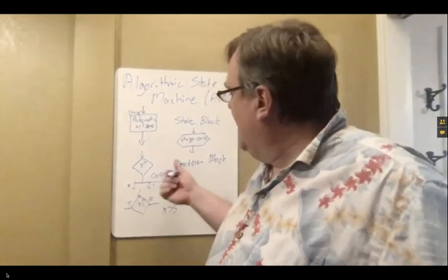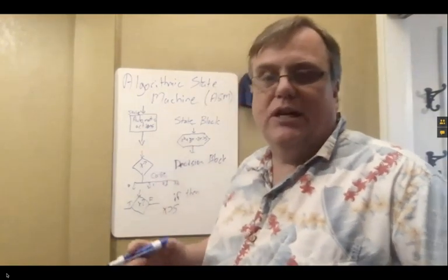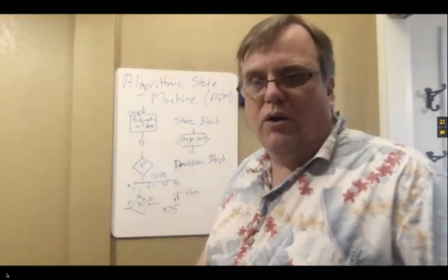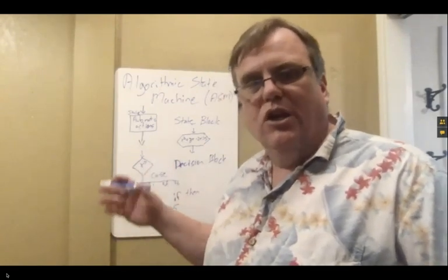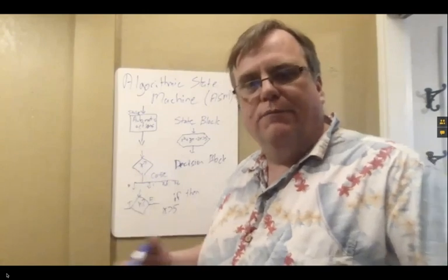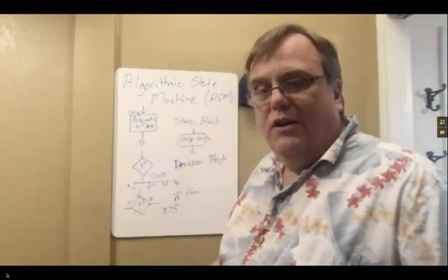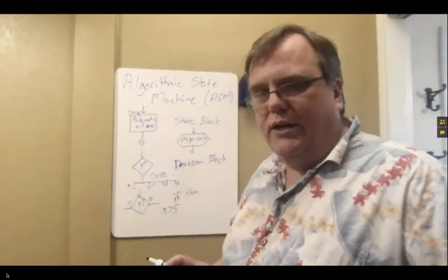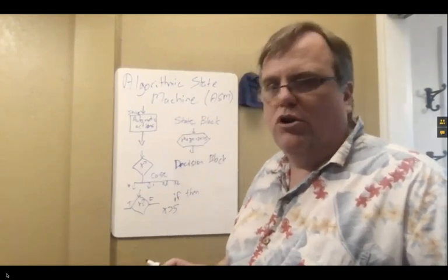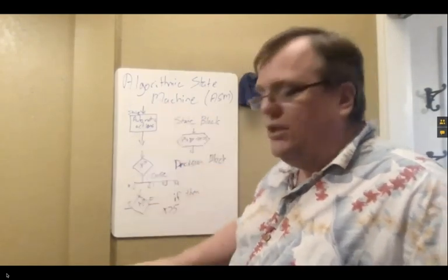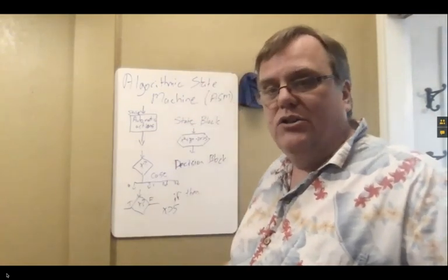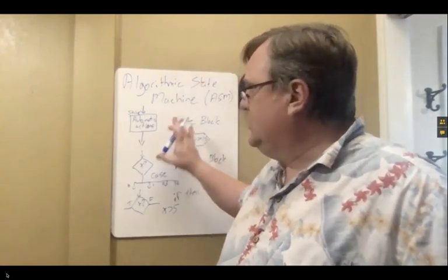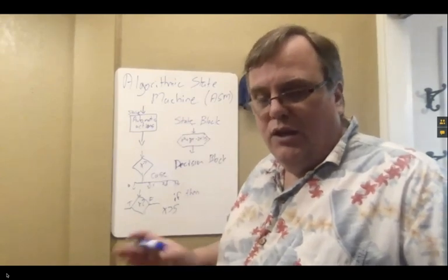The stuff today will also be very testable, which is why I wanted to rush things up so I got through this and you have time to test it, because ASMs are actually one of the easiest ways to write Verilog code from. You can almost just look at the thing and write them, and very complicated designs can be made very simple by ASMs.